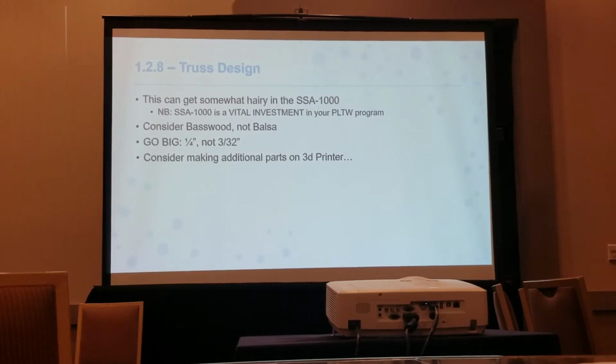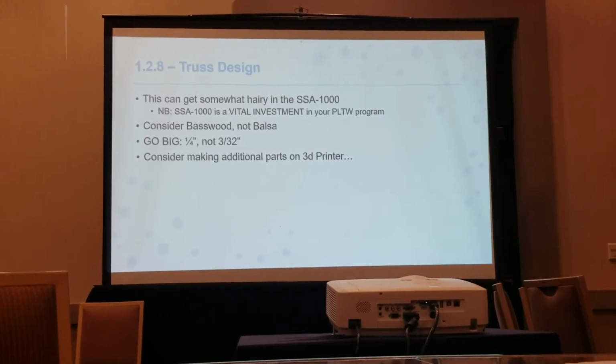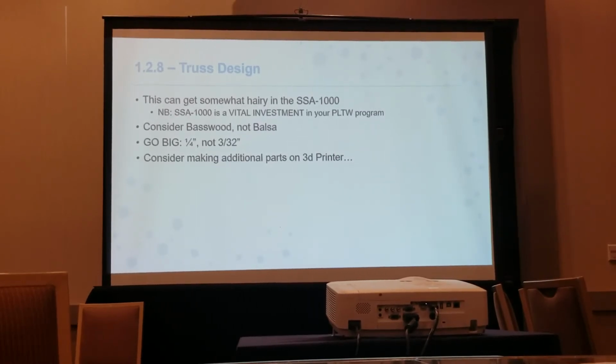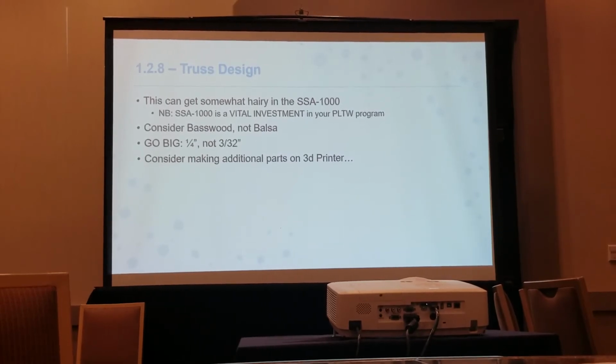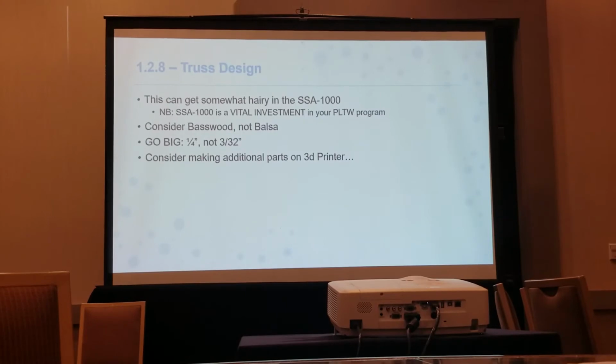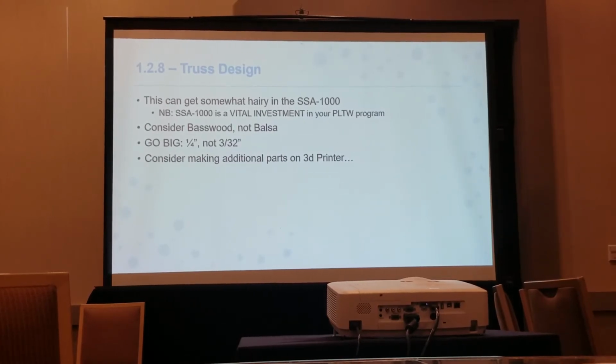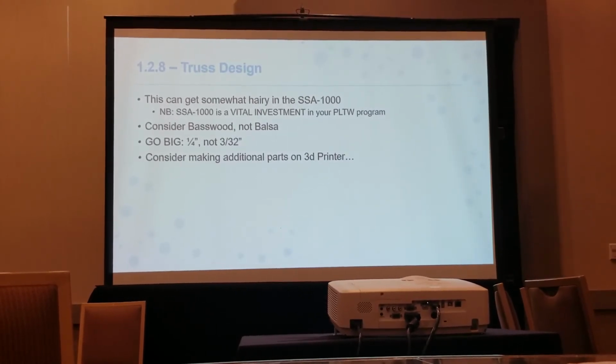Because you could start the plate up here, and this isn't deflection. It's not deflection until it actually starts bending whatever you're testing, or pulling on whatever you're testing. Because from the force deflection graph that it gives you, you can actually calculate a stress strain. Quick Excel stuff in your group.